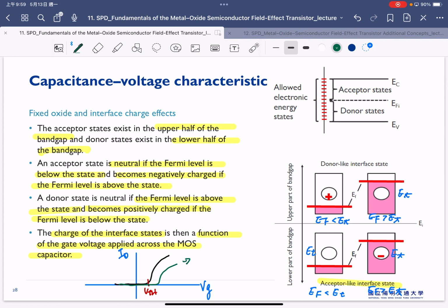This is a case of negative charge in the acceptor state. The original full explanation we can consider is a negative charge in acceptor state, but to simplify this phenomenon, usually we don't always call that the negative charge in acceptor state. This is a very long description, so we can simply refer to this as electron trapping. So this is exactly the case like here. Once we have electron trapping, we can foresee our threshold voltage is increased.